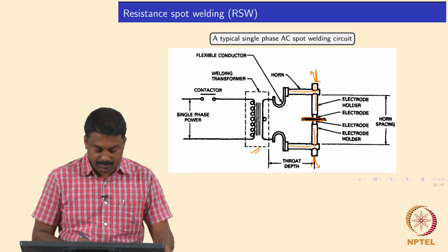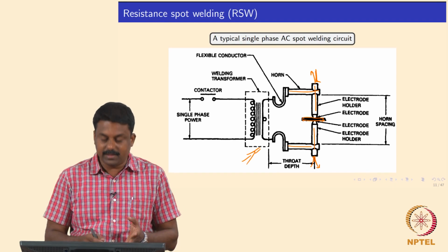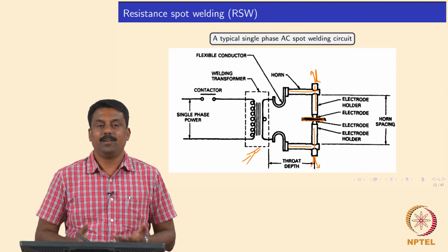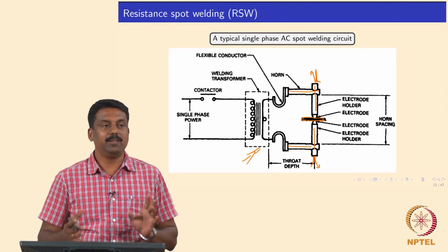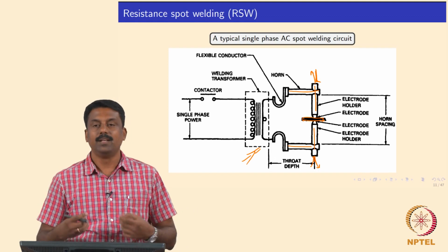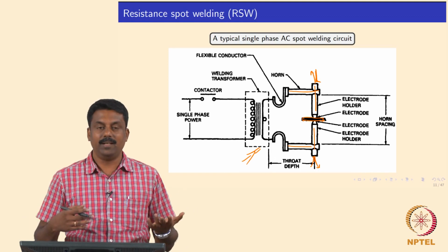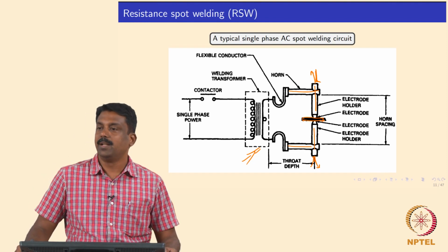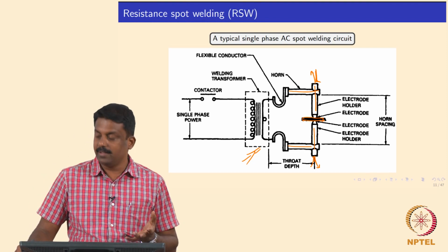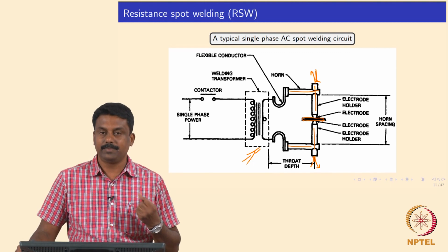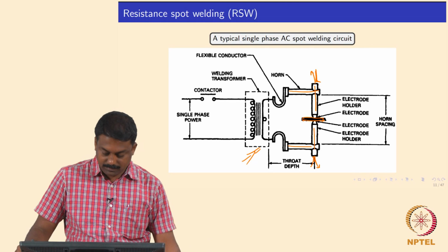Nowadays this transformer circuit is also microprocessor controlled. So we can play around with the ramping time, cool down time, post pulsing, number of pulses, squeezing load and then cooling load. Everything can be varied based on the program we use. It's clear? Good.